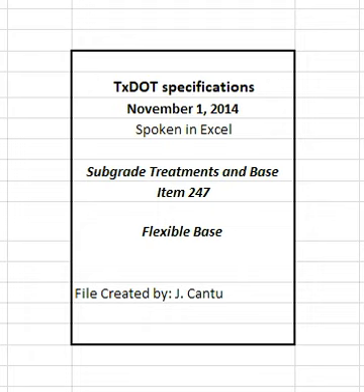5. Measurement. Flexible base will be measured as follows. Flexible base, complete in place. The ton, square yard, or any cubic yard method. Flexible base, roadway delivery. The ton or any cubic yard method. Flexible base, stockpile delivery. The ton, cubic yard in vehicle, or cubic yard in stockpile.